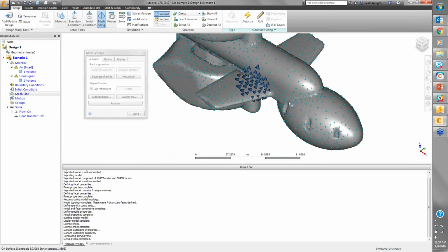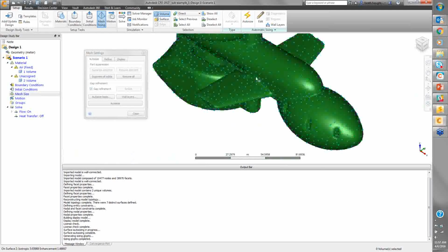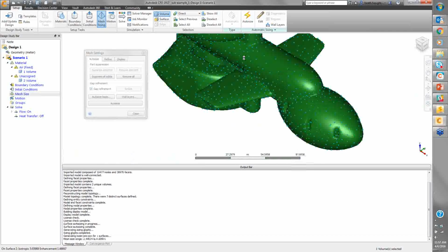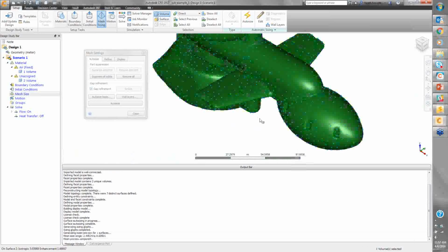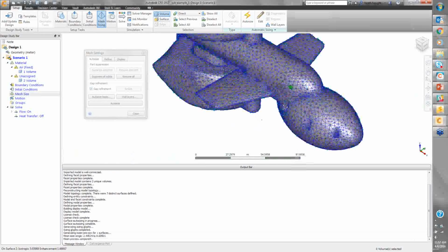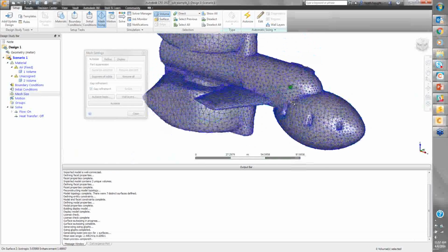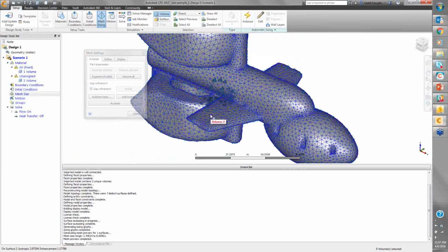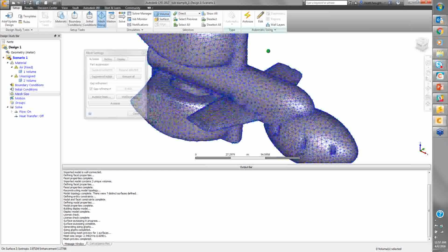I want to look at a collection of those elements to see the overall distribution. I want to look at a preview of what that mesh really looks like. You can see it right there. So there are 3 levels of preview: these dots now represent relative mesh density. We can do the grid, which shows the size over specific regions of the model, or we can fully preview like we could in regular models.